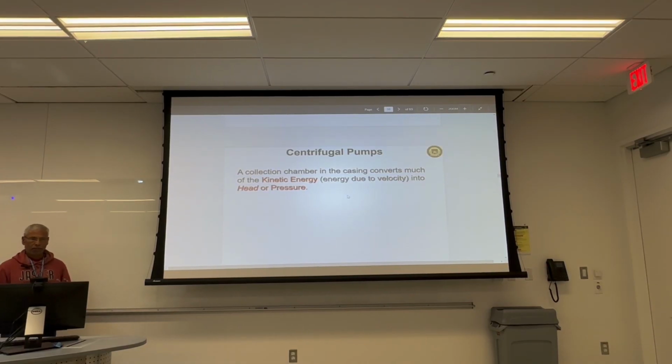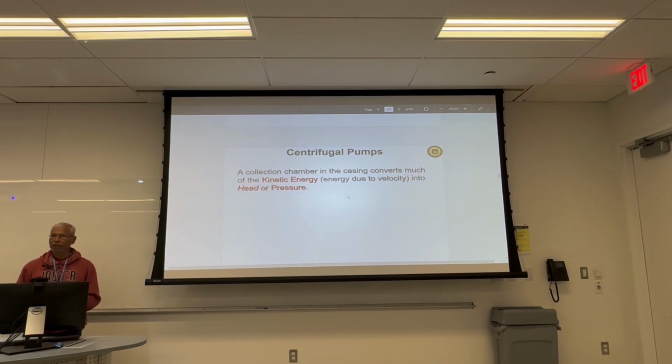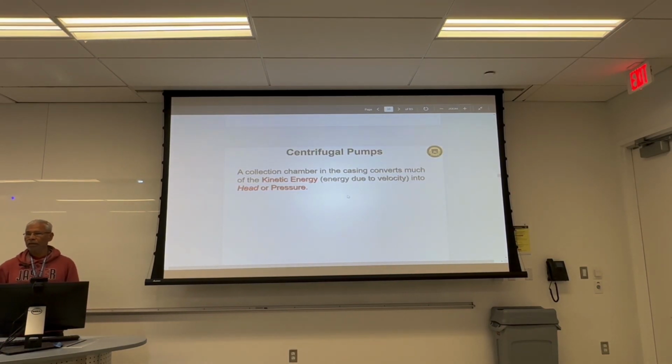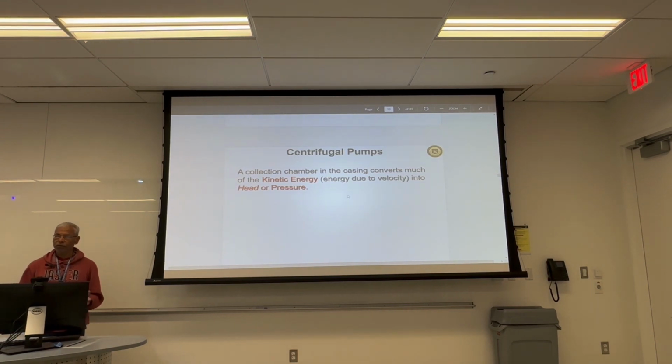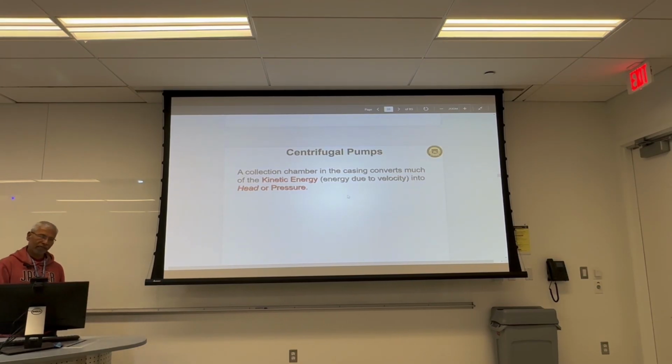You need a certain pressure, because if you don't have pressure, you cannot push the fluid further. If you want to push the fluid up a 100-foot-tall building, pressure has to build up, and the casing acts like a device to convert the kinetic energy into pressure head.